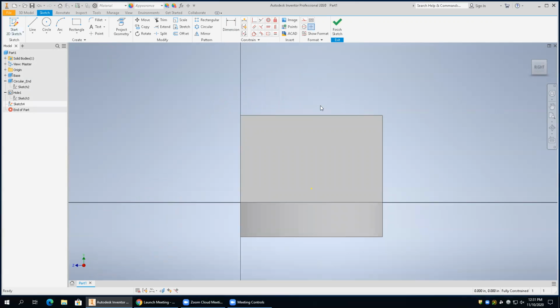I'm going to generate now a rectangle. So I'm going to come up here and do a rectangle. I want to make sure that corner of the rectangle is touching that face, so make sure it gets a good connection there. And then bring that down. Don't worry about the distance. Okay. So it should be locked into that. We're going to now throw some dimensions on there.